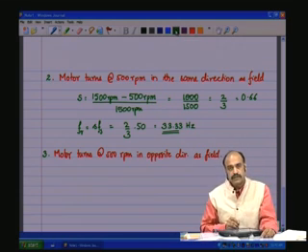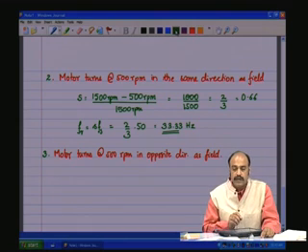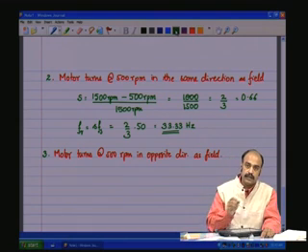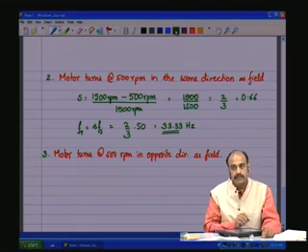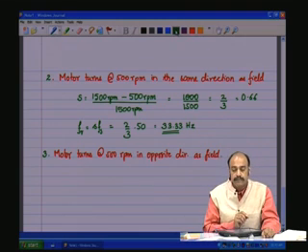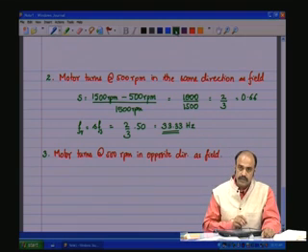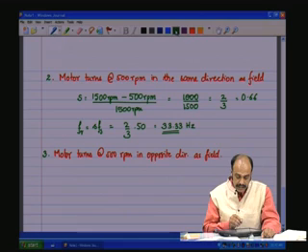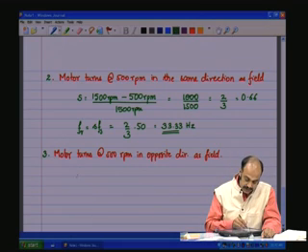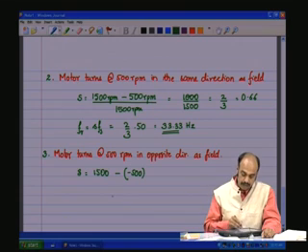So if the rotating magnetic field is rotating in a counterclockwise or anti-clockwise direction, which is considered as positive by convention, then let us say the motor shaft is rotating in clockwise direction, then it is minus, and therefore we have the slip now, which is 1500 RPM minus of minus 500 RPM. See the negative sign here.